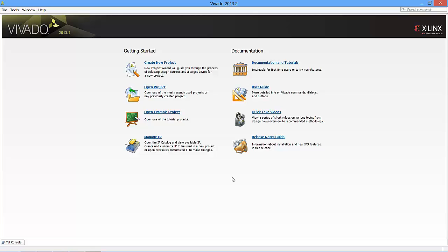Welcome back, YouTube. We are now opening the Vivado software. We'll go ahead with the first step, which is to create a Vivado project. We will name the project Lab 6, targeting the ZedBoard Zynq Evaluation and Development Kit, and using the VHDL language.